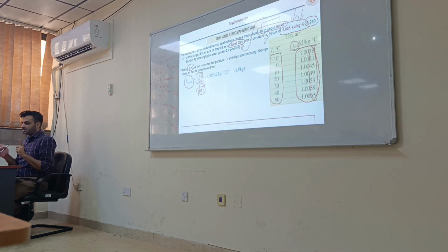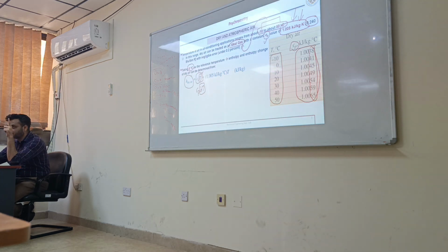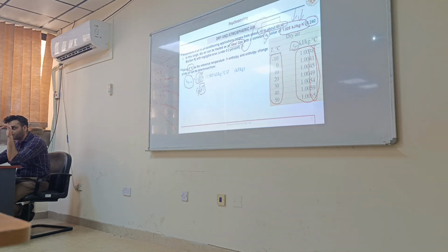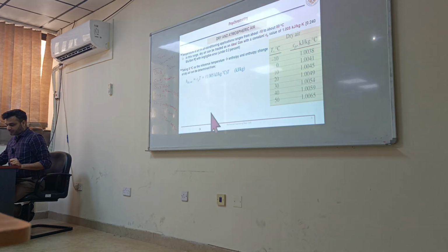Because in dT you have two T's, add 273 here, 273 here, those will cancel. Okay. So the single T which is remaining is Celsius now, not Kelvin. Okay. So you must be very clear about it. Okay.